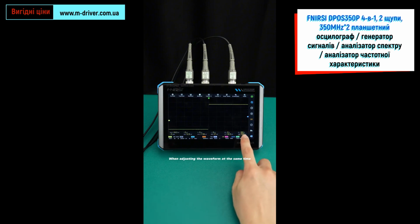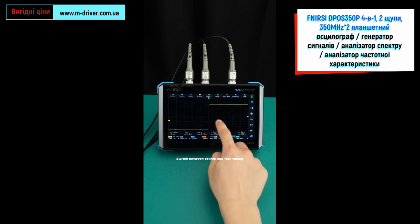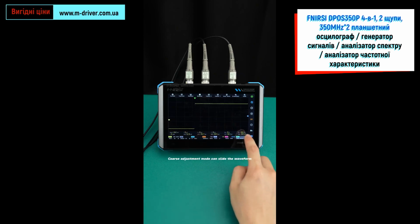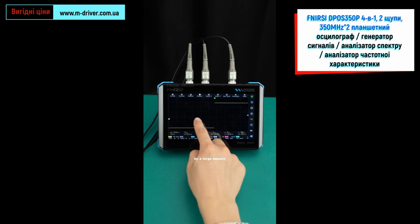When adjusting the waveform, you can click Move in the lower right corner to switch between coarse and fine-tuning. In fine-tuning mode, you can slide the waveform slightly. Coarse adjustment mode can slide the waveform by a large amount.